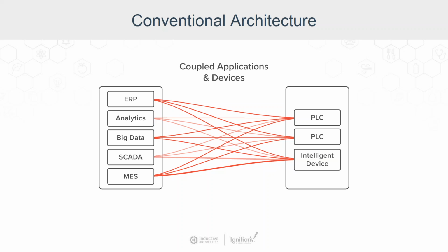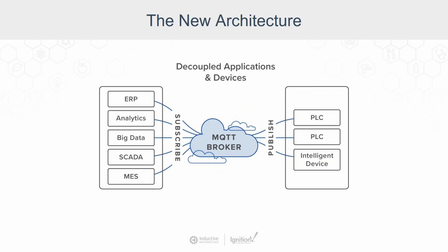As I mentioned earlier, we want to be able to connect devices to infrastructure. And the way we do that is to have devices publishing data to message-oriented middleware, such as MQTT. We're going to be talking a lot more about that here today. That is an open protocol that is a publish-subscribe methodology where we can have the PLC sensors and the data publishing its information to an MQTT server, the middleware there, that then there can be many consumers of the data who can subscribe and get access to it.